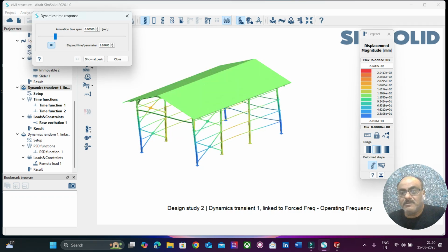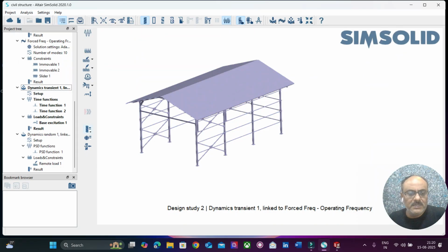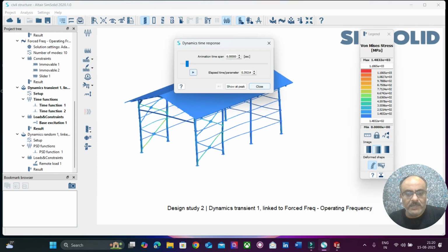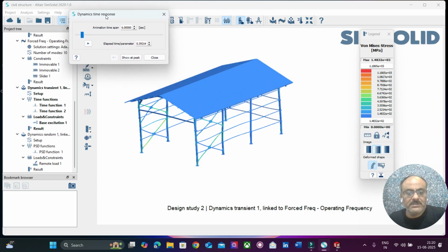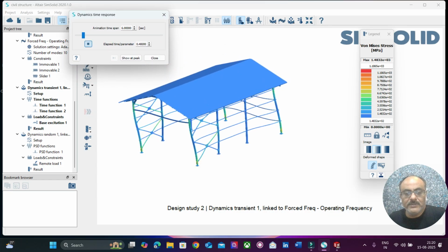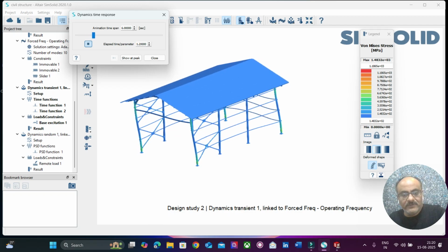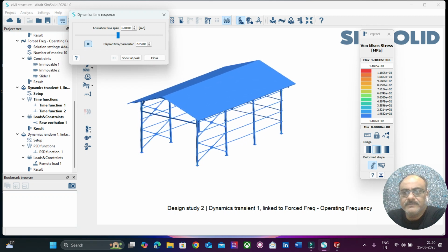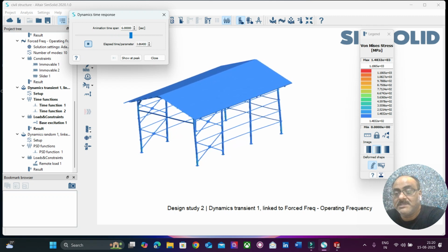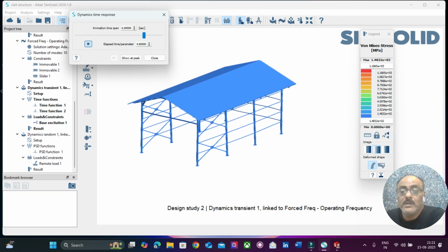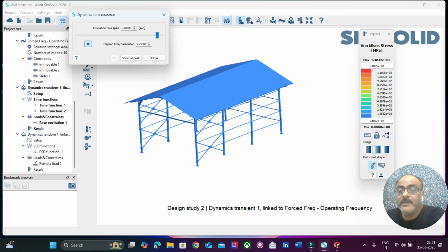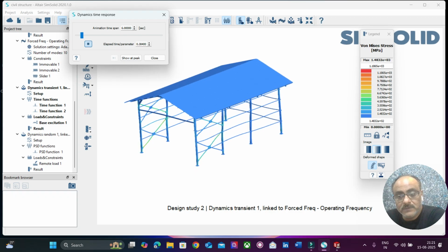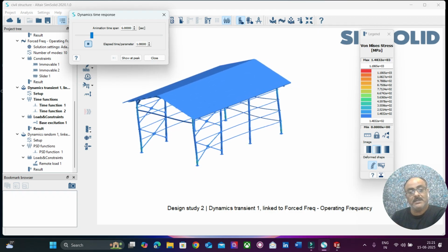The displacement is enormous, 254 mm. So it's about 25 centimeters. It's a very big value. Now this is how the structure is going to get stressed. You can see that every member is getting distorted. And then here we find the volumetric stress is about 118. Not 118, it is in fact 1186, which is almost 4 or 5 times the yield stress of the base material, steel.